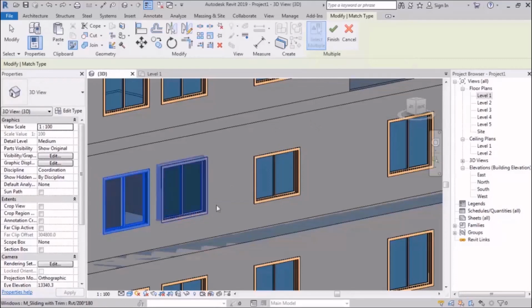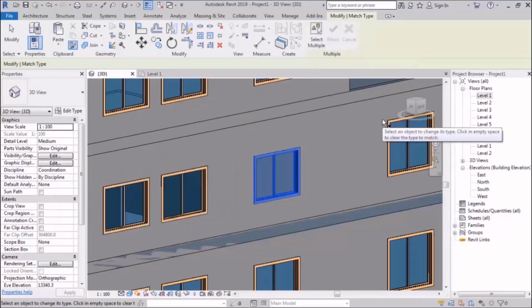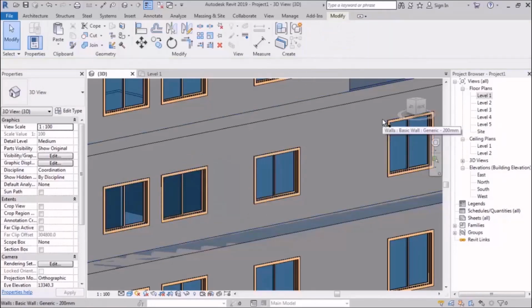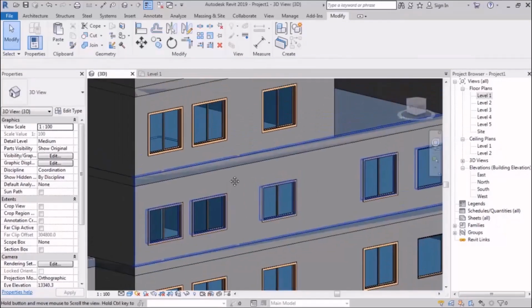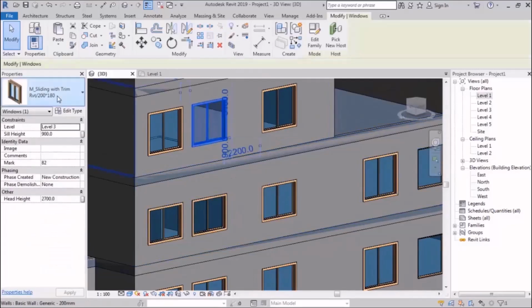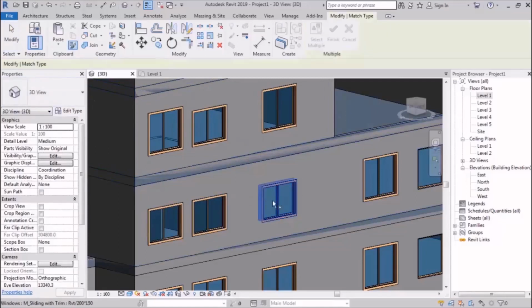You select it and after selecting them, then you click on finish. So we duplicate only when we don't have that model. Alright, if we have that model, we can select it and move it from properties or use the match properties, this one and then this one, and that's it.